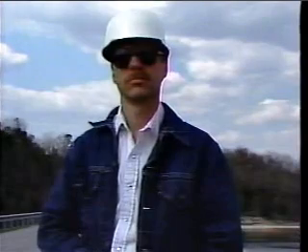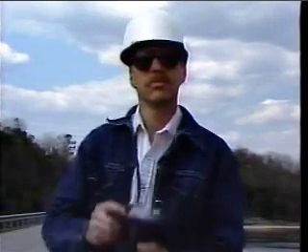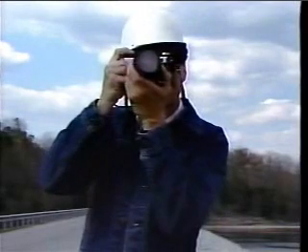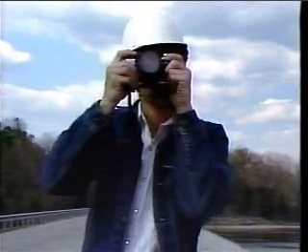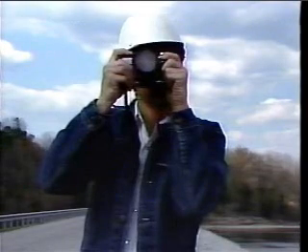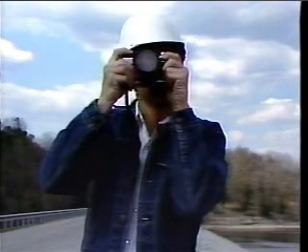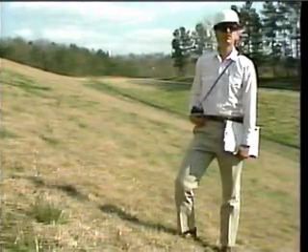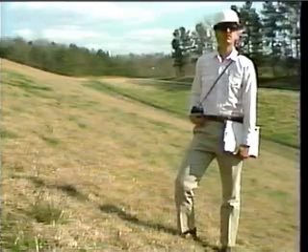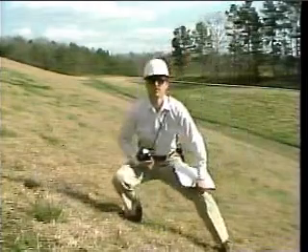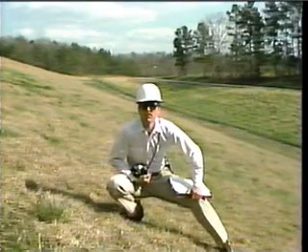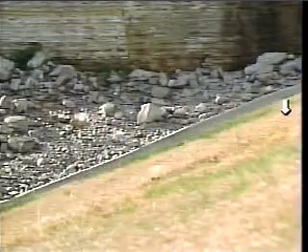You can also take a photograph with a telephoto lens. Notice how the foreshortening makes the depression stand out. Another technique for identifying distortions of slope or crest is ground level viewing. Let's see what that might look like. By sighting along the crest and slope surface with your eyes near ground level, misalignments and irregularities will stand out in relief, and you'll have a much better chance of spotting them.